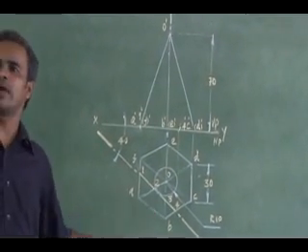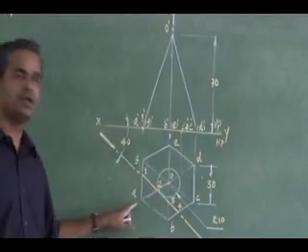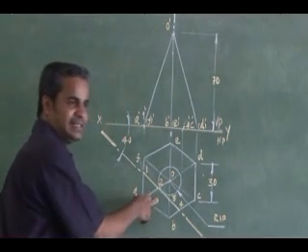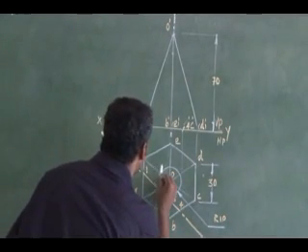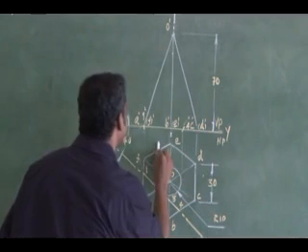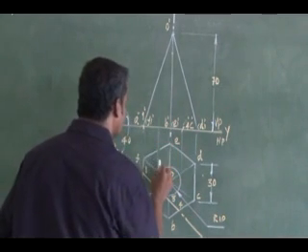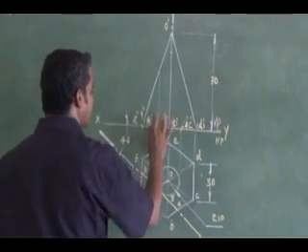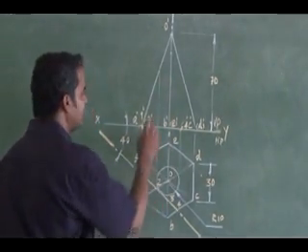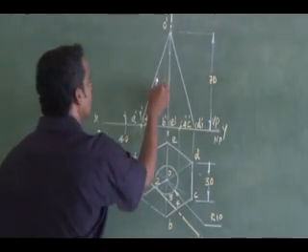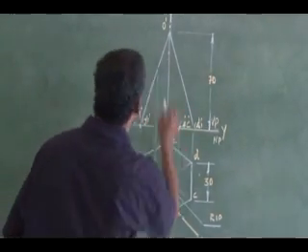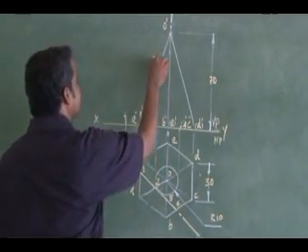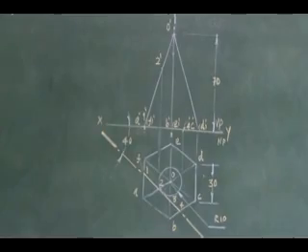Then this 2, listen all of you. How can I project it? Cutting point 2 is on AO. So the AO slant edge, the cutting point 2 can be projected vertically to the front view, to the projector line. Wherever it meets AO in the front view, that is my cutting point 2 dash, here, cutting point 2 on AO.